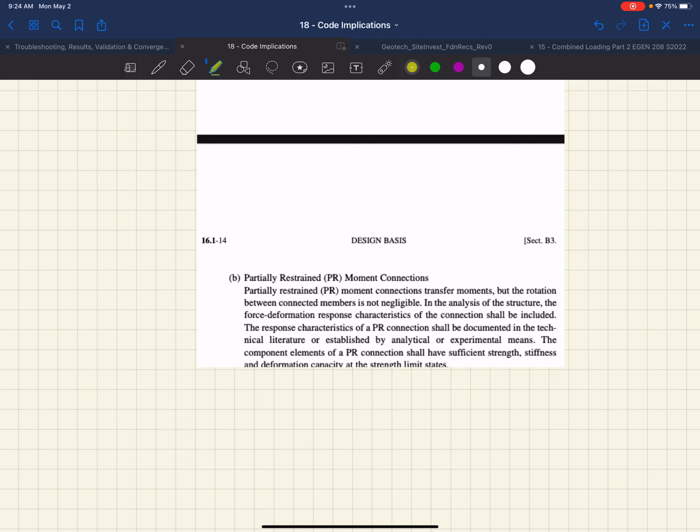So in 360, I don't know if in steel Damon had talked about it, there's a whole section in the steel manual at the beginning that's all about simple shear connections. And it walks through all of these different types of connections. Double angle connection, they have stiffened seat connections, they have shear tab connections, they have extended shear tab connections, they have all these different connection types. And in each of those connection types, they tell you, hey, you need to consider the moment on this bolt group, because in some of the connections, they're designed and there's limits, like there is for the thickness of your shear tab, okay?